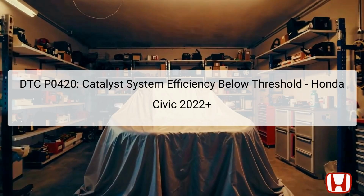The upstream oxygen sensor monitors the level of oxygen in the exhaust before it enters the catalytic converter, while the downstream oxygen sensor, referred to as HO2S, Heated Oxygen Sensor 2, assesses its output post-processing. If the readings from these sensors indicate a fluctuation that exceeds the threshold, the Powertrain Control Module, PCM, triggers the P0420 code to alert the driver of a potential emission control issue.